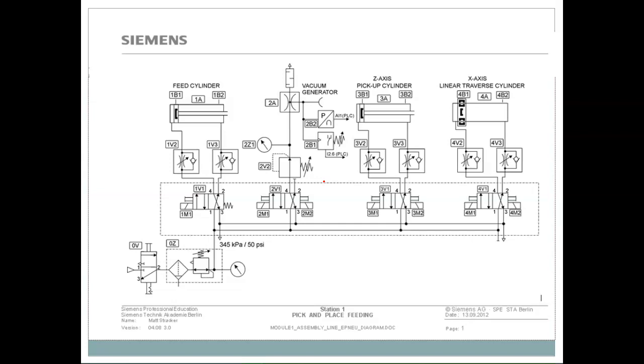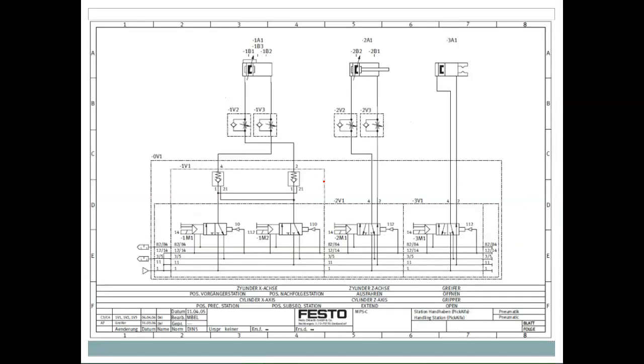All right, we've got a vacuum generator and two other cylinders. Meter out is probably one of the most common assemblies of these. Why? Because it means that we can keep the cylinder moving in a very smooth way. Because you have control over how fast the air leaves, you also have control of how fast it can enter. So it's very smooth. Once it starts moving, it's just very easy to go. We'll talk more about that when we get to that.